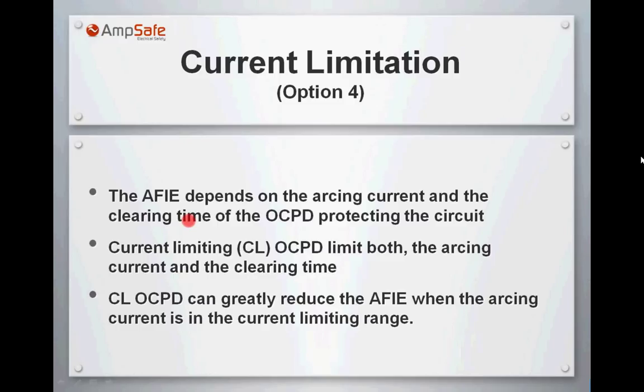So the current limiting overcurrent protection devices can greatly influence your calculations, depending upon the value of the arcing current.